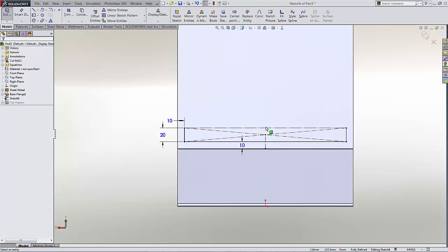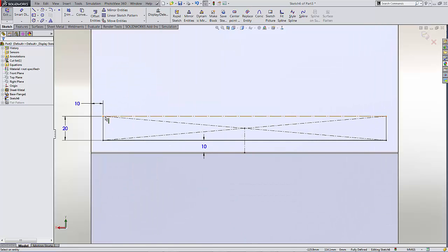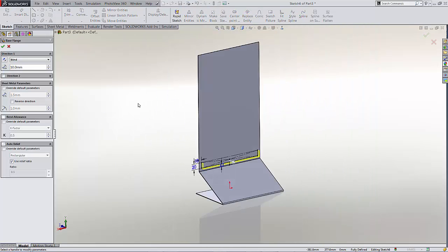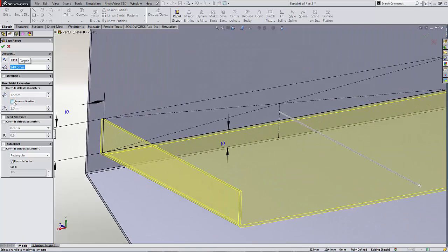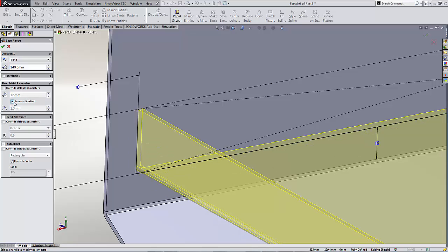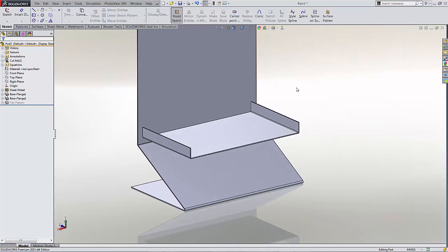So basically SolidWorks ignores it. It won't build from dotted lines, it'll only build from solid lines. So hopefully you can see that we've got 3 solid lines here. It's like an upside down hat. Then all I'm going to do is extrude that as well. So again, using sheet metal, I'm going to say that perhaps we want it to be 140 deep. Again, I can specify which side of that line my material is. You can see here I can toggle between inside and outside. We're going to go for inside, and then I can accept it, and that's created our next piece of sheet metal. What I want to do is to turn up the front of this shelf.